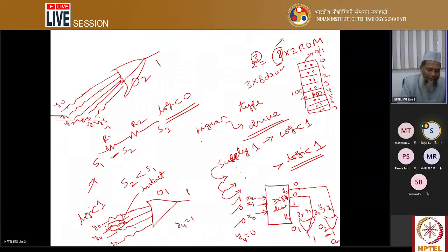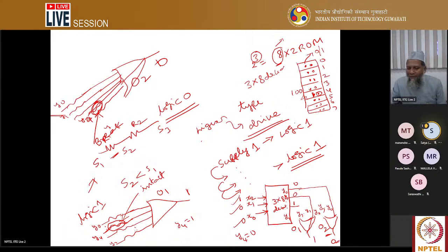So what you have to do is break the connection corresponding to Y4 for this gate. Then the line where the 1 is coming is broken, and all the remaining inputs are zeros, so the output is 0. If you want to store 1, you have to keep all the fuses intact. If you want to store 0, it depends on the combination: whichever output is 1, that corresponding connection has to be blown. You have to break that connection. Then the output will be 0.